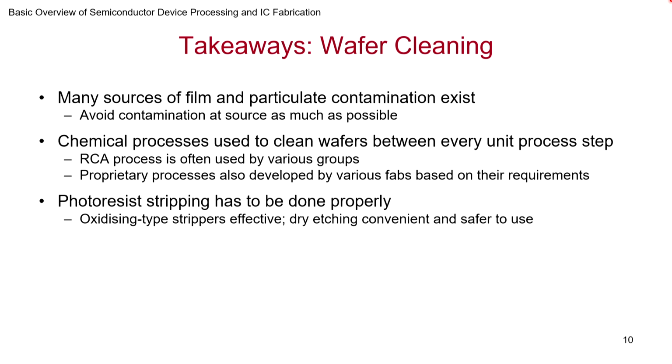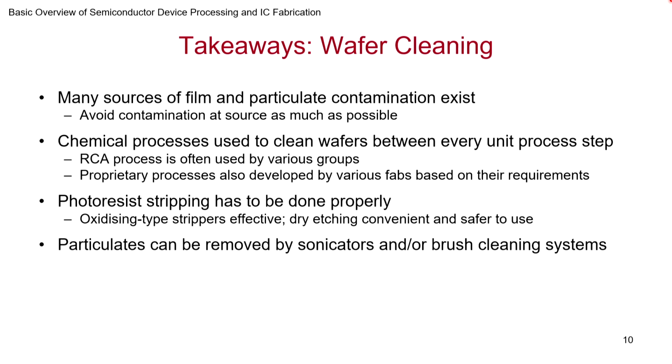Photoresist stripping has to be done very properly, because you are coating something on the substrate and you have to remove it, and you have to make sure that what is to be removed is completely removed. Oxidizing type strippers are usually effective, but dry etching is more convenient and is used more nowadays. Particulates can be removed by sonicators or brush cleaning systems.